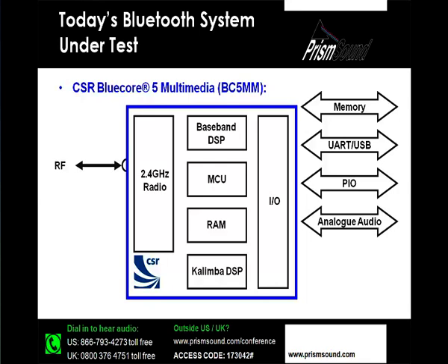We've also got analog audio input and output. We've got on-chip microphone amplifiers, so we can interface directly to microphones, and we've also got an on-chip power amplifier, so a headset device will only need this chip and microphone and speaker plus a few passives.